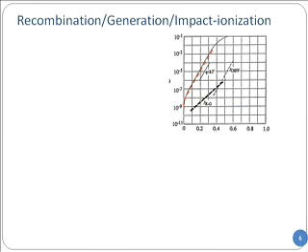So what I explained so far is the IV characteristics in the diffusion or thermionic part of the device, right? And you can see the slope of that region is q over kT as soon as the applied voltage is a little bit high, because then the minus 1 will be negligible, and then you can do a log-linear plot, and that will have a slope of q over kT, very similar to the diffusion in the p-n junction. Do you remember that?